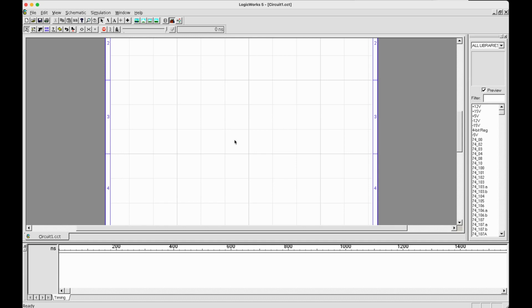Let's take a look at how to implement some of the basic functional blocks we have covered in this lecture. First of all, we have value fixing. To show you how to do value fixing, let's first get a binary probe as our target. Let's say this is the wire upon which we want to fix a constant value of 0 or 1. In fact, let's copy this and do 0 here and then 1 for this wire.